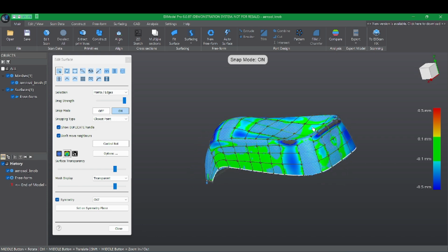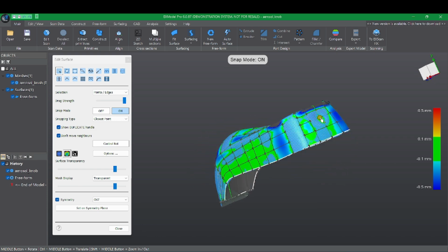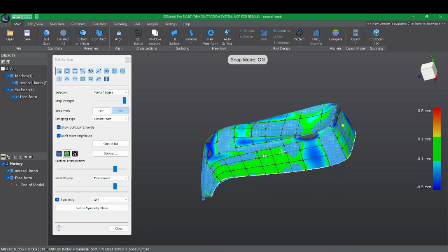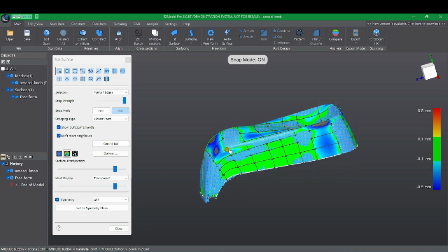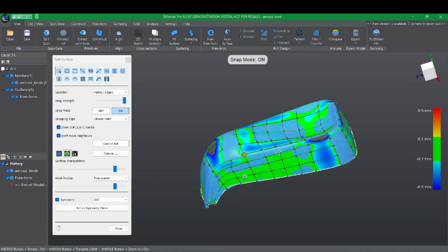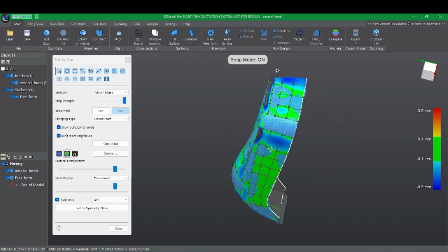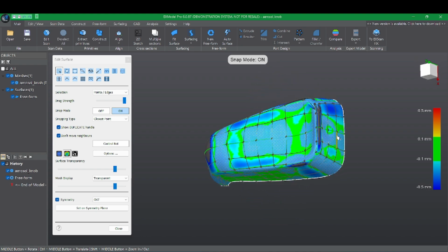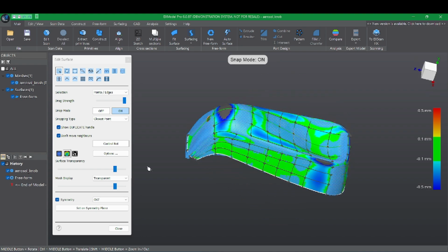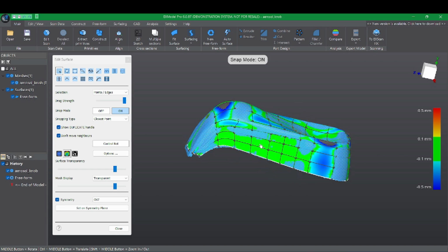You can also try to move the points over the mesh so you can improve, or if you double click you can move the whole edge chain, or you can just take one single edge and move it, and all of them will actually be projected again. This is not working now. Again, as you see, they don't really move because our option don't move neighbors is enabled.